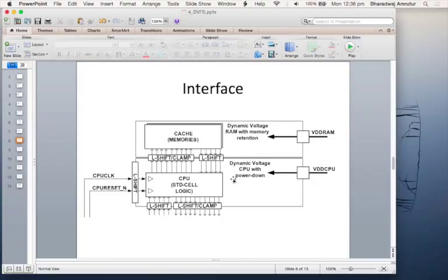Now when you disconnect that particular block, what happens to the internal supplies? Let us say there is some switch out here which disconnects the external supply from the internal supply. So this internal power supply voltage, what will happen to that? That will start dropping. It's like one big capacitor, no one is holding it, and because you have leakage happening, it will slowly discharge that internal power capacitor.